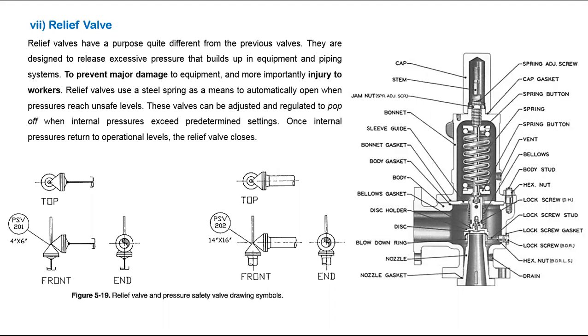For 6 bar pressure, our plumbing fixtures will not support it. All fixtures will support up to 4 bar only. So if you want to support 10 bar or 6 bar, you have to use metal pipes. You have to invest more cost.